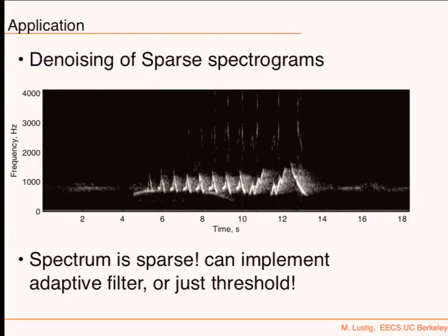Mask it. So threshold, right? Is that what you meant? So I can threshold this signal. That will give you just the simple operation of thresholding, giving me effectively an adaptive filter. If you think about this, an adaptive filter that adapts to the signal, right? And it will be kind of like a bandpass filter, right? If I threshold, then I would just go around. And if you think about this, it is automatic adaptive filtering that would occur if I just do this nonlinear operation of thresholding in this domain.